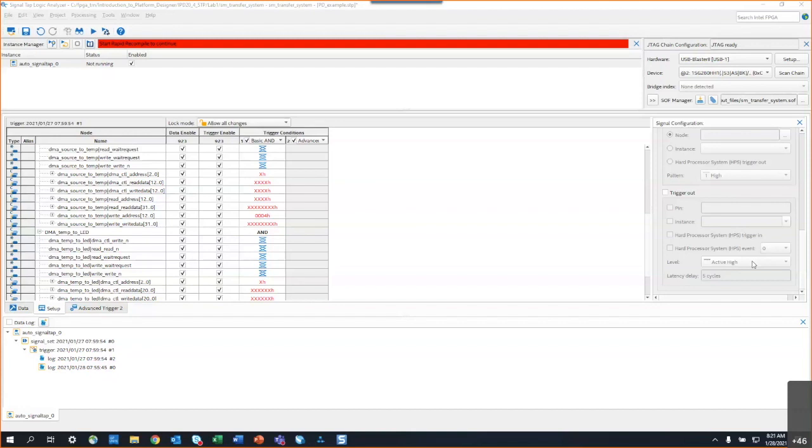So what you're saying is that you're seeing transitions on the middle clock that you're not expecting to be seeing. Is that what you're saying? Right. Exactly. So that makes me go back to timing. Is your design meeting timing closure? I need to look into that. Thank you. Yes. It's possible that your design is not meeting timing, and that you're getting transitions that are happening too late, so they're getting sampled by the incorrect clock from signal tap.